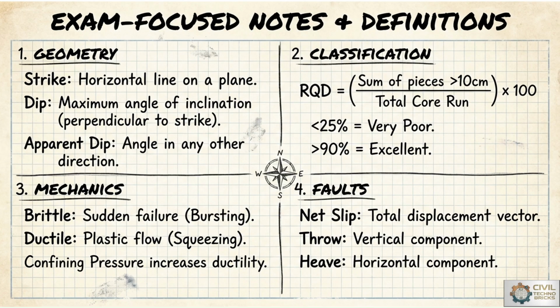The geological treatment improves stability and safety of tunnel foundations and surrounding rock. Grouting is a method used to reduce permeability and strengthen the fractured rock. Rock bolting reinforces unstable rock blocks around the tunnel openings. Drainage systems control groundwater pressure and seepage problems. Proper treatment measures increase tunnel life and reduce maintenance requirements.